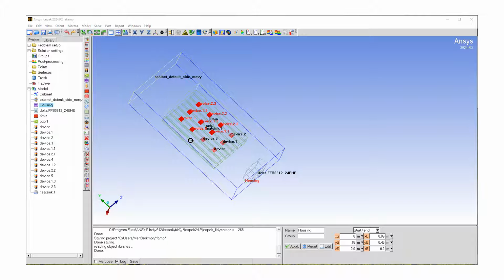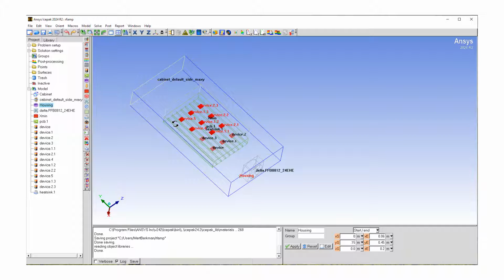Next step, once the geometry and the components are defined, is meshing. For meshing, a lot of times we want to do some assembly strategy, which has two benefits. One is better meshing. You can assign different meshing properties and sizes to different assemblies. The other is a better structure.